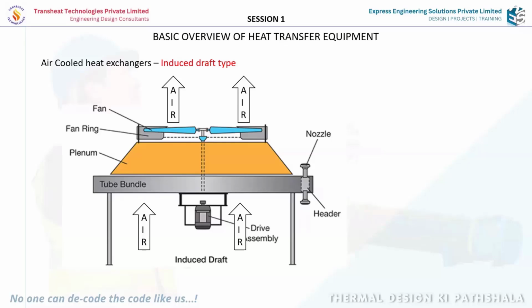So this has some considerations for the fan blade material selection and any other instrumentation and control items which you can have on top of the induced draft cooler units. So there are considerations for the air exhaust temperature in induced draft units if we have some downstream equipment or instrumentation on the induced draft unit.